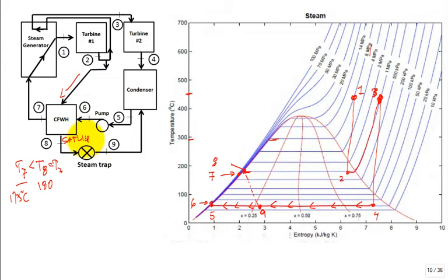Saturated liquid. This is either way you would say it's compressed liquid, or I'd probably call it subcooled liquid. It's at a very high pressure, is it not? What's the pressure at 7 compared to the pressure at 1? Yeah, it's the same. So it's at the 8 megapascal. It's hard to show it, all those lines tucked in there, but it's at that high pressure.